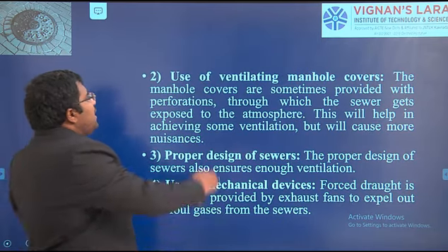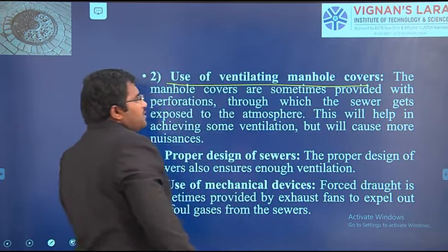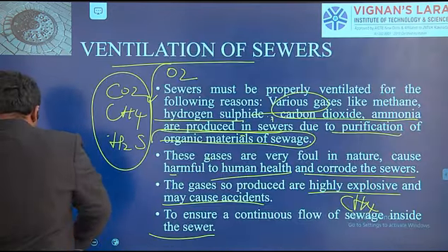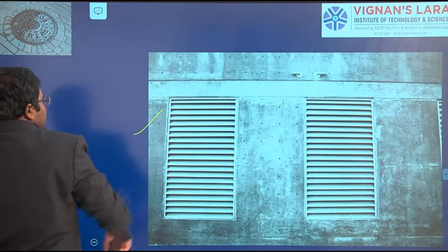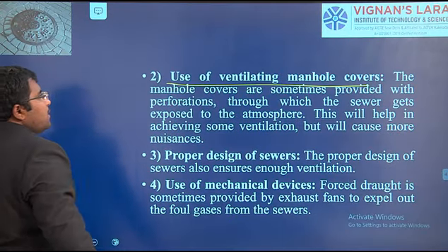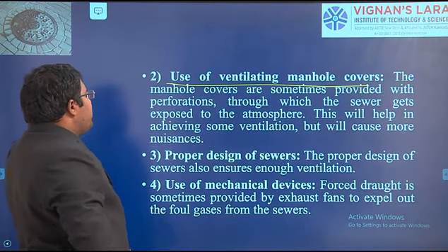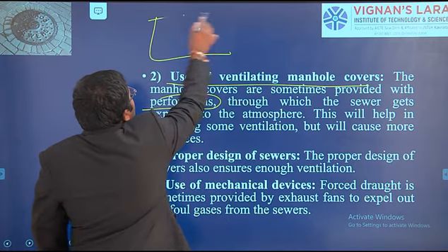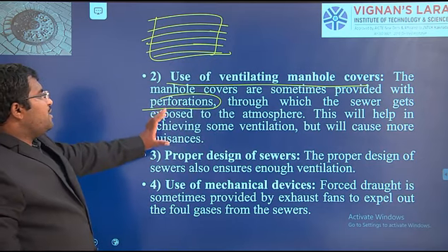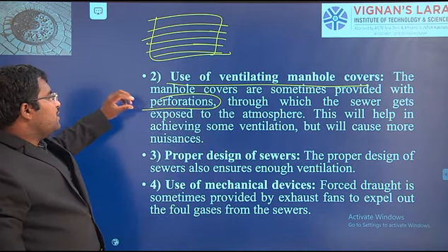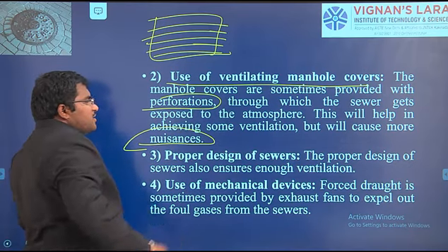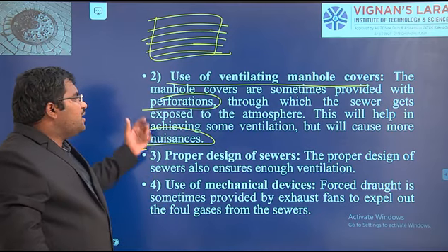Next, use of ventilating manhole covers. The first photo you observed here is a ventilating cover. The manhole covers are sometimes provided with perforations, the kind of openings we saw, through which the sewers are exposed to the atmosphere. This will help in achieving some ventilation, but will cause some nuisance because the smell is continuously coming out.